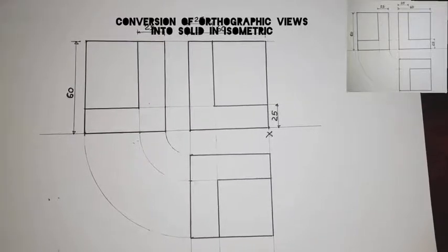that we are going to draw is viewed from the right; the end elevation is viewed from the right for it to be drawn on the left. Now we are going to take X as the lowest point to draw the views in isometric, and the question reads: the above are orthographic views in first angle projection. Draw a solid figure in isometric, showing the views given in isometric projection. So let's proceed.